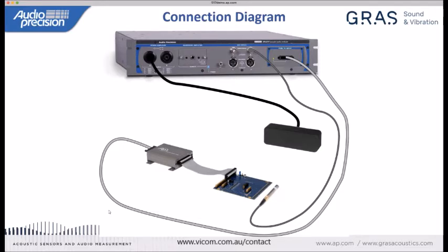When a 1/4-inch pressure field microphone is 90 degrees incident to the sound field, it will actually have a flat response to 20 kilohertz even in a free field. So that's sort of another advantage: the smaller the microphone, the more flexibility you have with how it can be positioned and used in different sound fields.